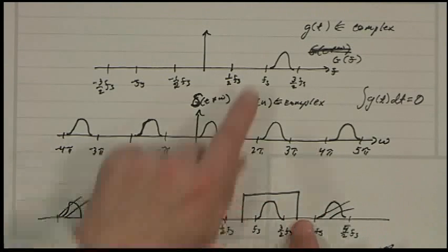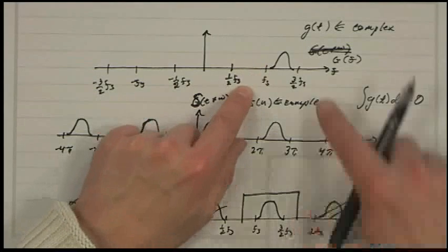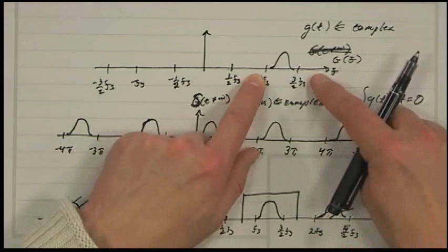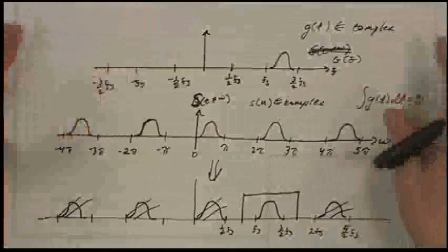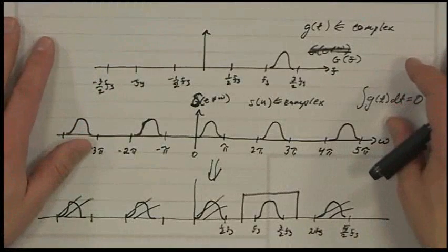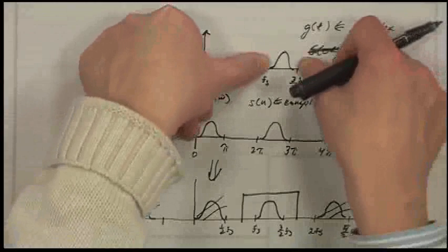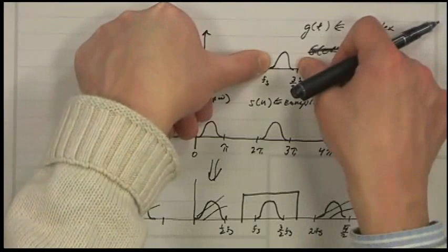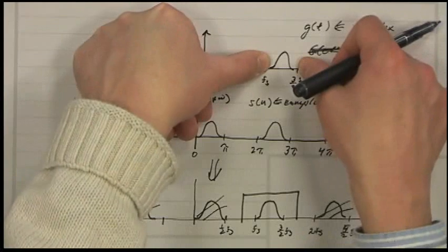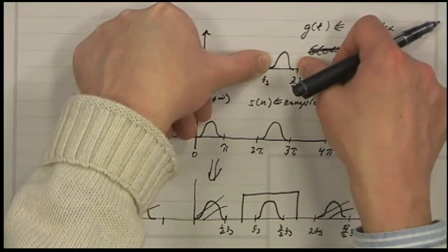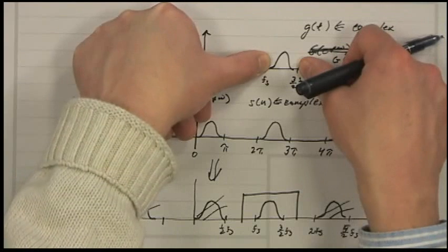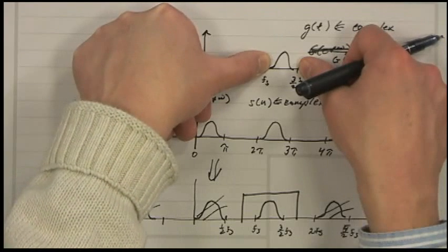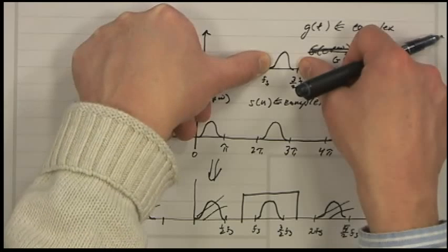And voila, you've reconstructed that signal, and I violated the Nyquist criteria because it was not band limited to half the sampling frequency. But somehow the spirit of the Nyquist criteria has been maintained, right? Because its total bandwidth was less than half the sampling frequency. In fact, in this case, the condition is that the total bandwidth has to be less than the sampling frequency. Okay, so